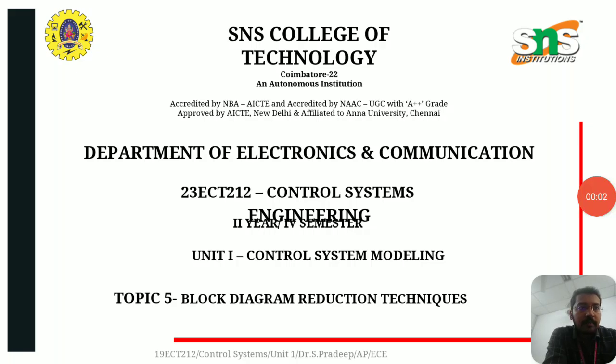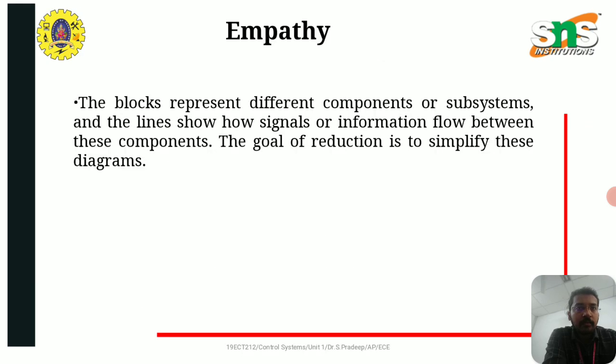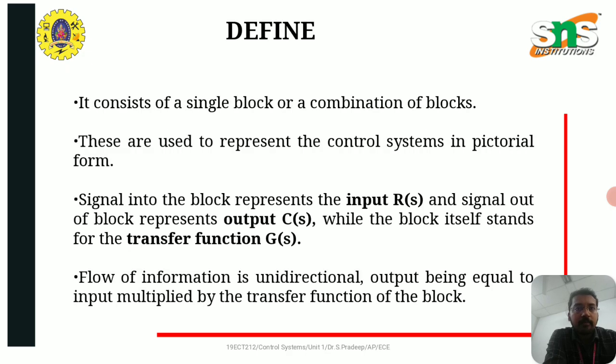Hi, in this video we are going to see about block diagram reduction techniques. The block represents different components or subsystems, and the line shows how signals or information flows between these components. The goal of reduction is to simplify these diagrams. It consists of a single block or a combination of blocks.